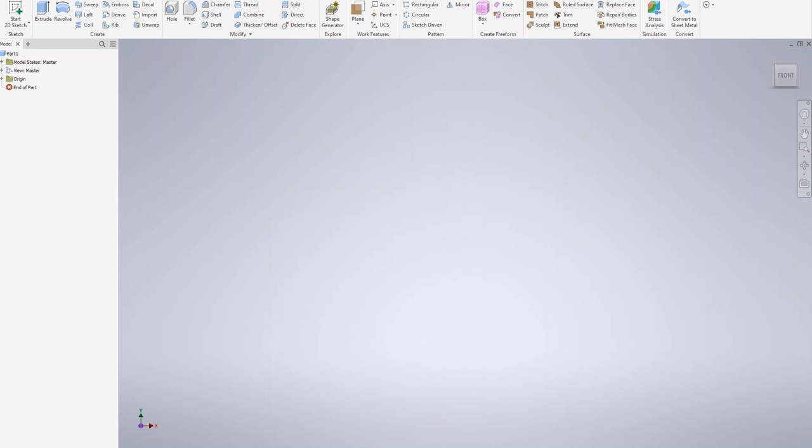So what do we do in Inventor? We start Inventor first, and we start the inch system. Go to the new command, select the English system, and under .ipt, which is Inventor part drawing, you start the .ipt in the English inch system. And after that, you go to origin.